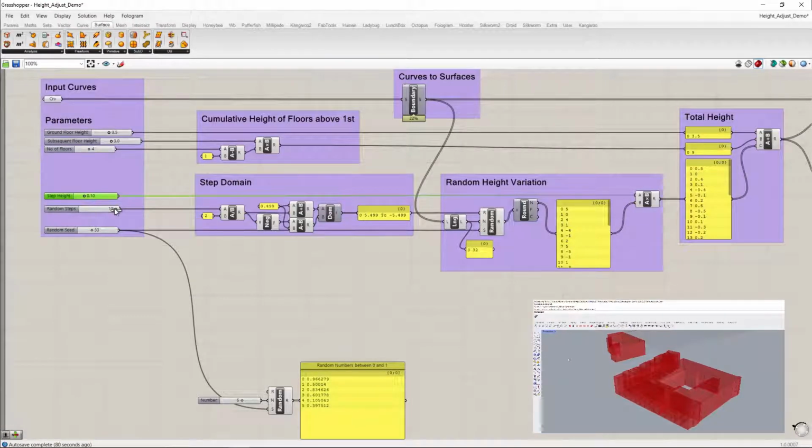We are going to divide the number of steps by 2, find the negative of this result, and use both numbers, adding 0.499 to the positive one and subtracting 0.499 from the negative one, to create a domain with a Construct Domain block. This addition and subtraction of 0.499 is necessary for us to get normally distributed numbers after rounding.